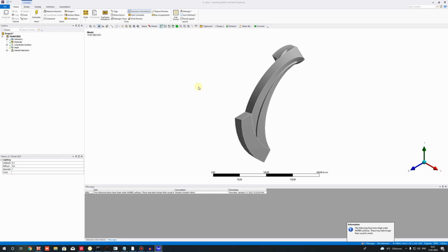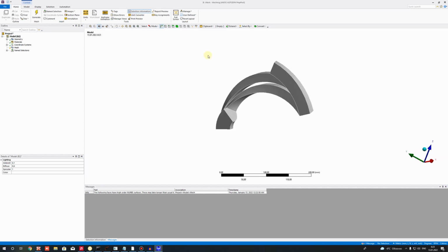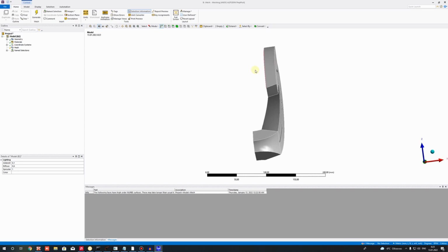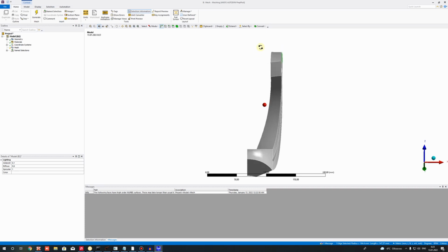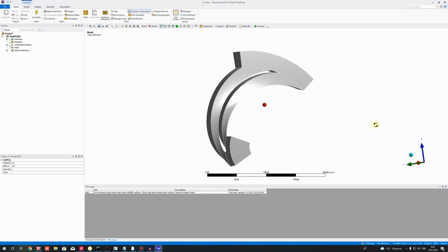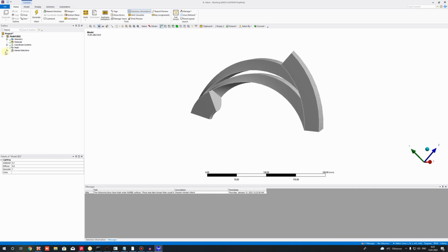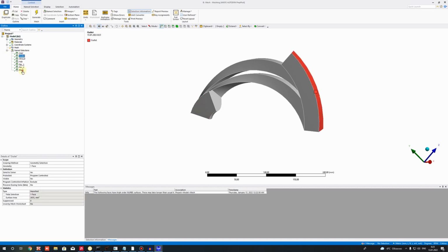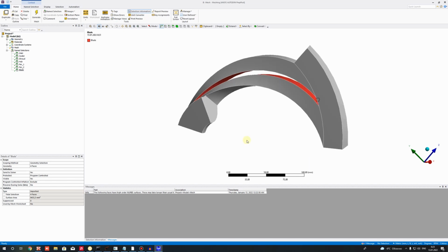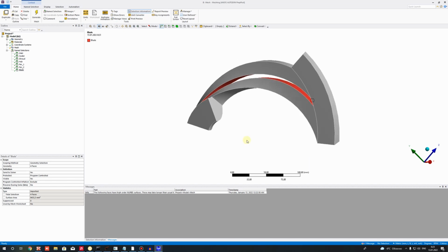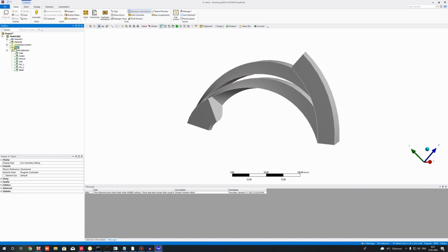And here we have our geometry with name selections in meshing model. In meshing model we have to set up the mesh for future simulation in ANSYS. So let's choose the mesh in tree, and in mesh we have to change the physics preference and set the CFD.